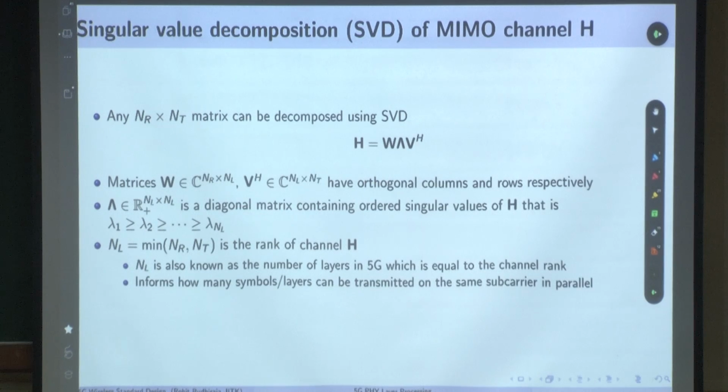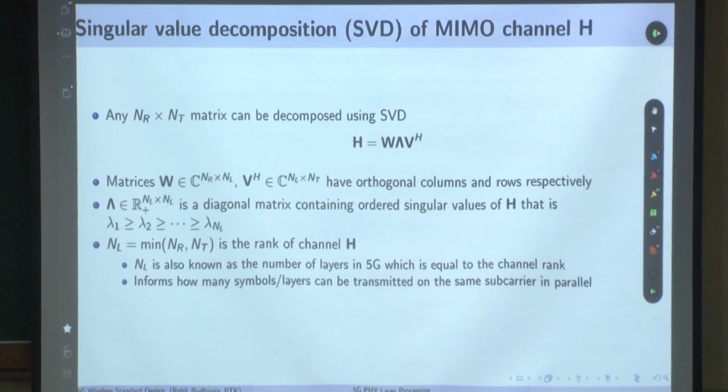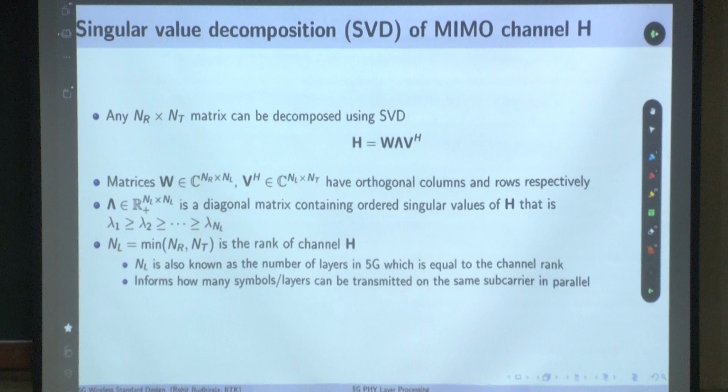Where is this important? It is important when your system is operating at a high SNR regime, and as we discussed earlier, in this high SNR regime, increasing SNR gives you diminishing returns, because you are not able to increase the capacity. Now you see this: with every doubling of antennas, my capacity gets doubled. From 1 to 2 antennas, I am transmitting double the number of symbols, which is essentially doubling the data rate, or the capacity. Similarly, if you make it 64 cross 64, your data rate becomes 64 times.